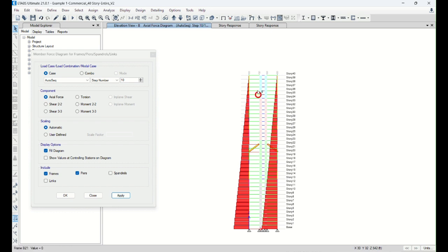So at that stage, this bracing is activated and holding some actual force. Since with this sequence analysis we just exclude it during the construction and tie this outrigger at the last minute, see the compression forces are kind of gradual again.